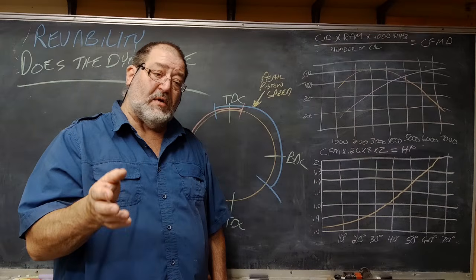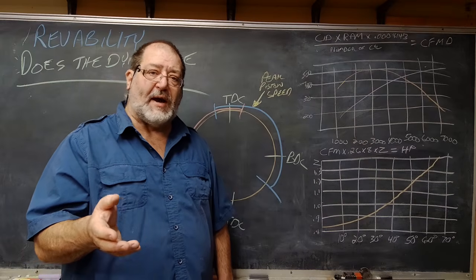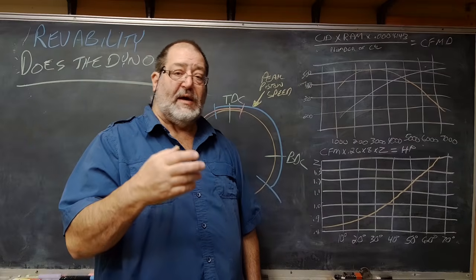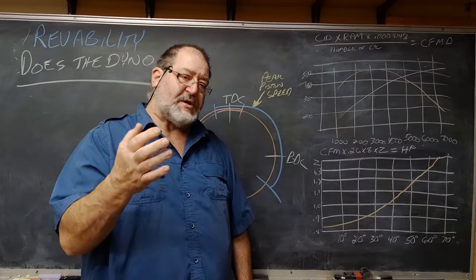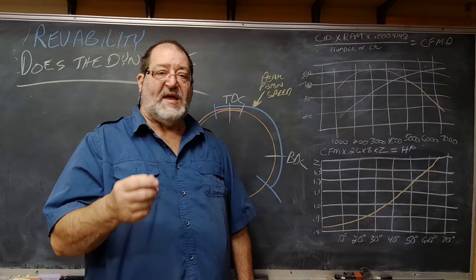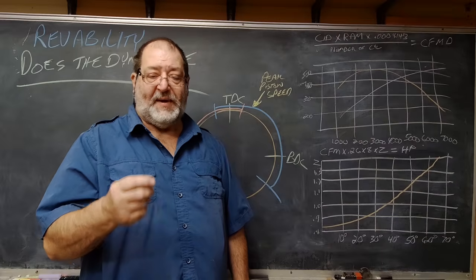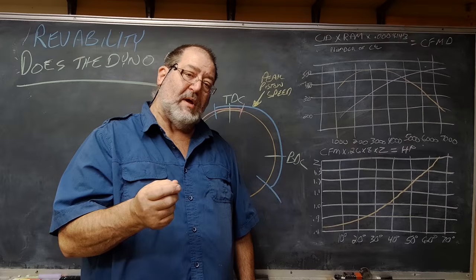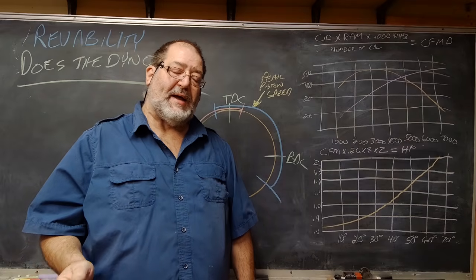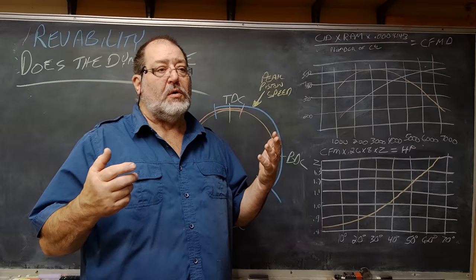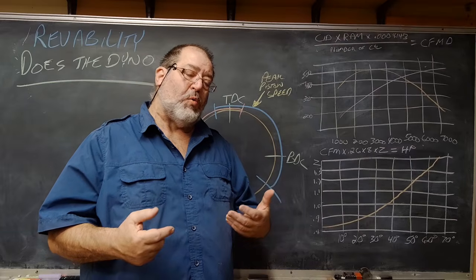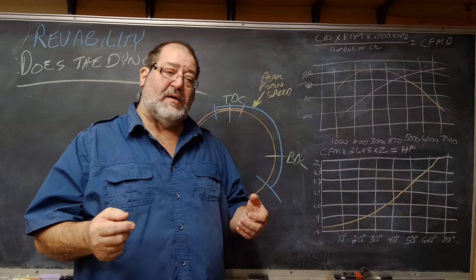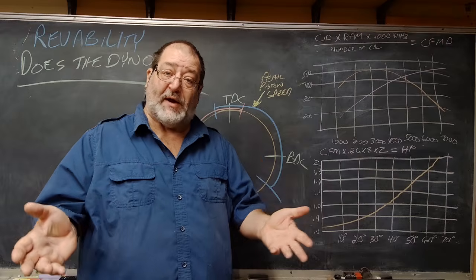And you can hear this even on the dyno sometimes, and see it on the graph, is you load it in, it kind of stabilizes, it starts to go, it struggles, and then you hit a certain RPM, which may be 3,000, 3,500, and it suddenly clears up and just goes. And so your airspeed got up to where things started functioning correctly and the engine started working better.